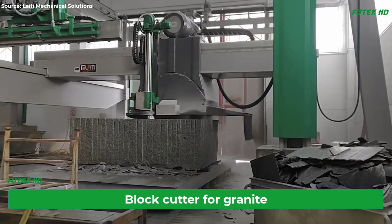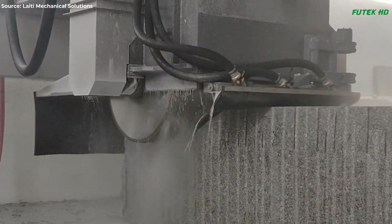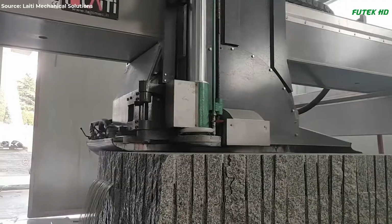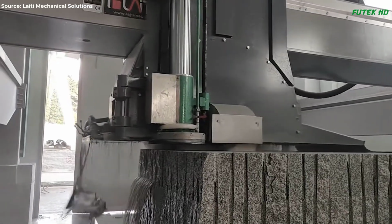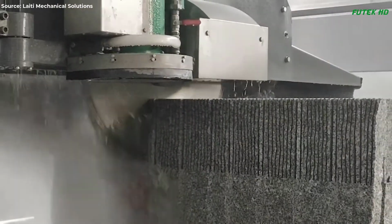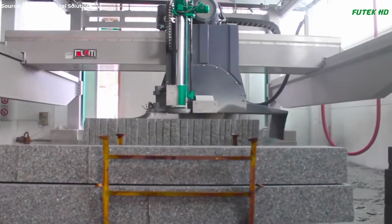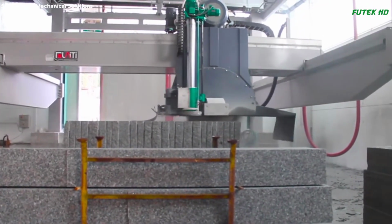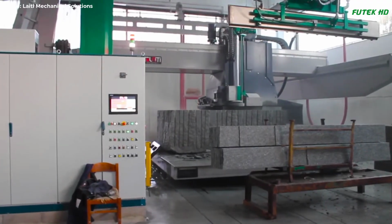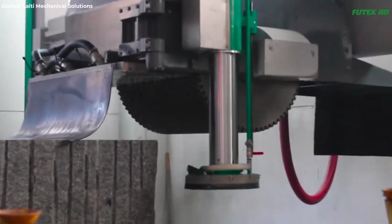A block cutter for granite is engineered to handle high sheet thicknesses and incorporates structures that minimize vibrations during cutting. It features gearing mechanisms to support the advancement of extra-large discs, capable of withstanding significant loads and reversals in movement. The disc trolley is fed on V-form guides, immersed in an oil bath and enclosed in stainless steel casing, providing superior durability and cutting precision compared to wheeled models.